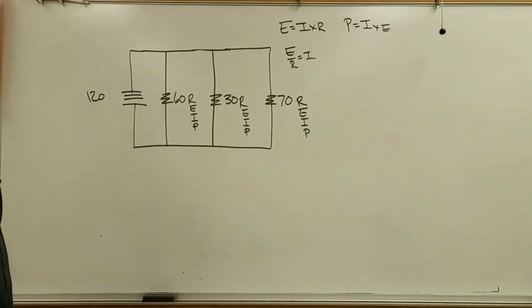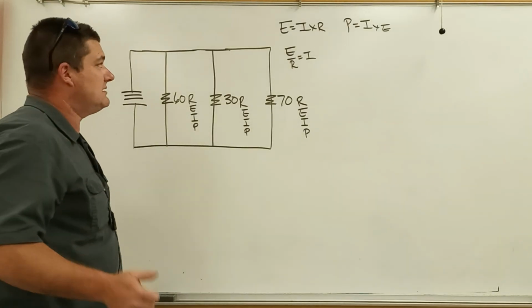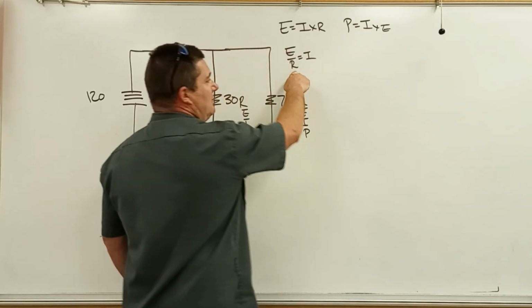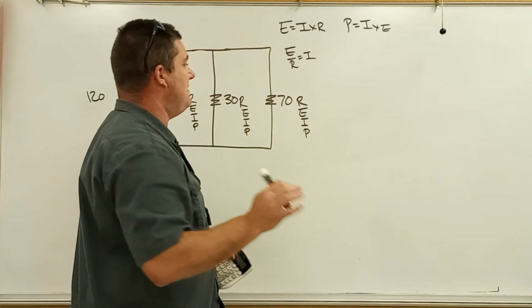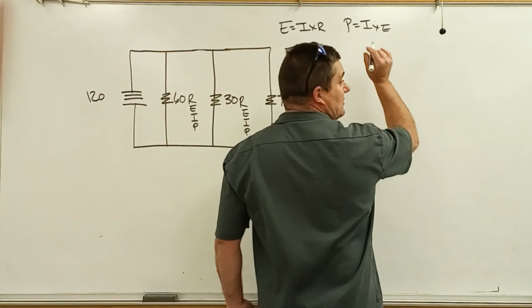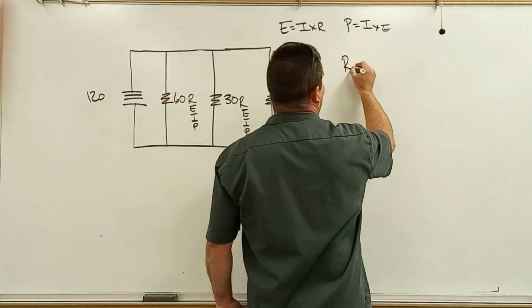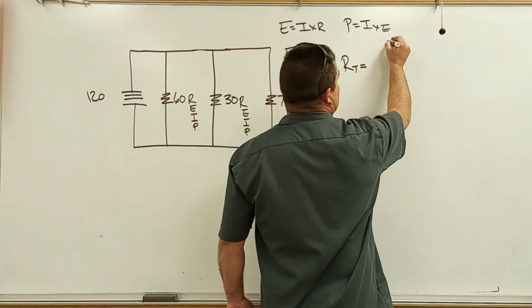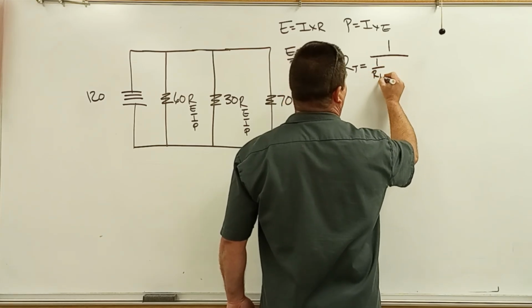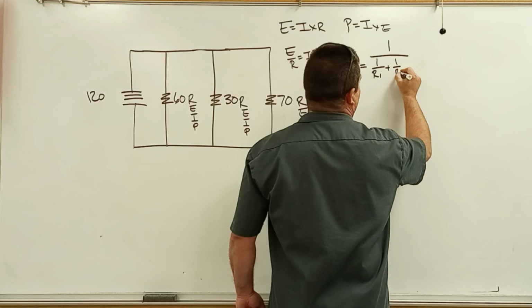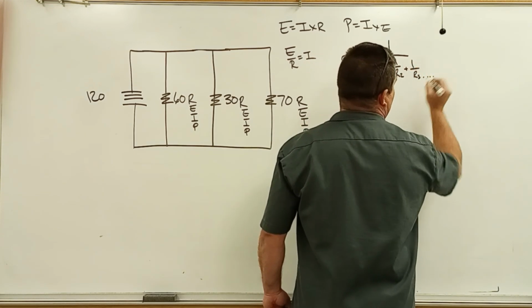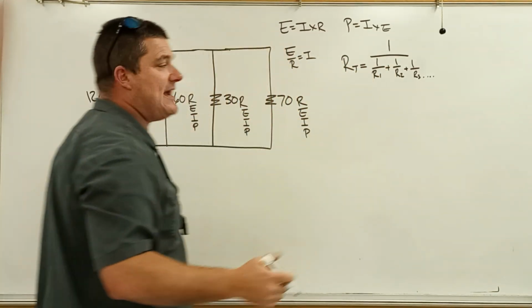Okay, Ohm's law, parallel circuits, Ohm's law, Watt's law, these still remain the same. You're still going to use that one to find your current. The significant change is adding the resistors in parallel. So this will be your formula: RT equals 1 over R1 plus 1 over R2 plus 1 over R3. And if you had more, you would just keep doing that exact same procedure.